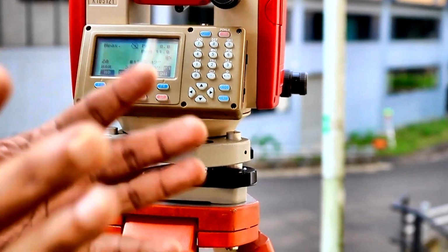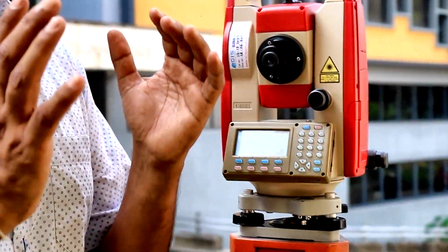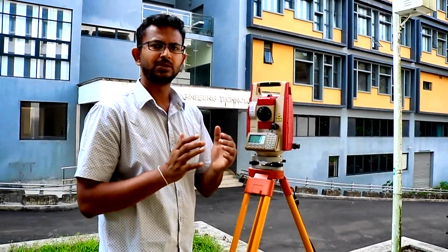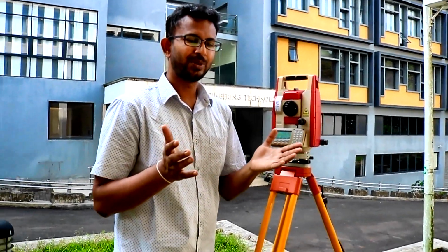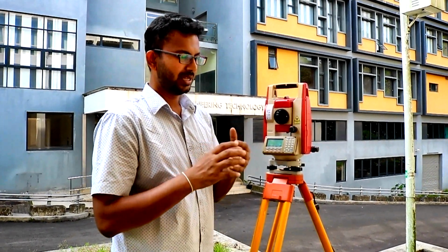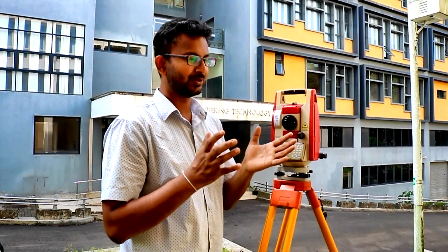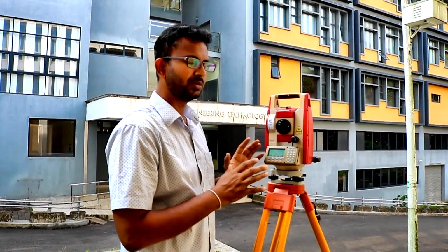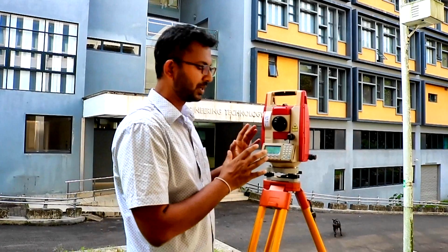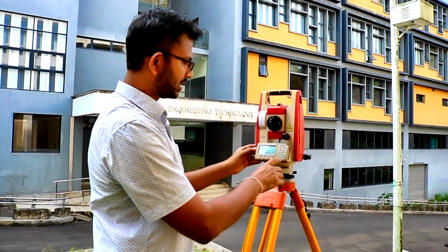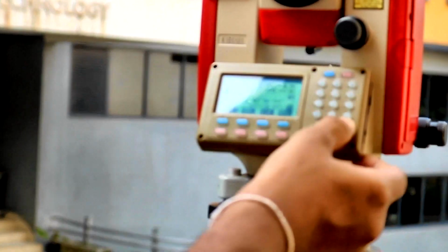Now I escape. First of all, before we start any kind of operation, we need to open a job, right? So now in your Word or Excel or whatever the application, soon after you open a Word document, the first thing is you save the document, right? In any case of the power cut or something, your file may not be saved, right? Therefore, first of all, we save the document. So similarly here we also need to create a file inside the total station memory, and we are working in that particular job, right? For that, here we have to press escape.